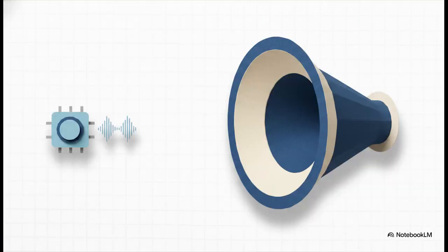To really conceptualize this failure mode, imagine two people trying to talk, but one is whispering and the other expects a shout. If a TTL chip outputs a high signal at 2.4 volts, but the CMOS chip receiving it demands at least 3.5 volts to even recognize a high, the receiving gate simply won't hear the signal. The circuit will just fail silently. No smoke, no sparks, just failure. This is exactly why matching those voltage tolerances is the absolute golden rule of interfacing.